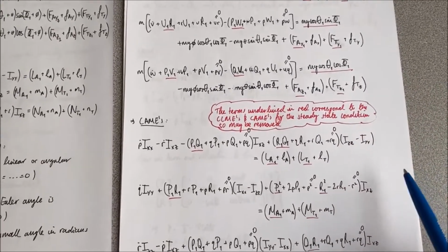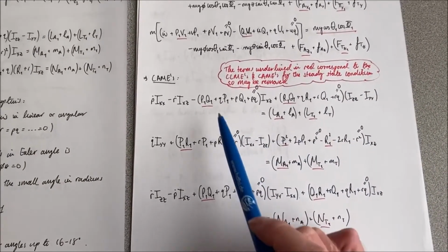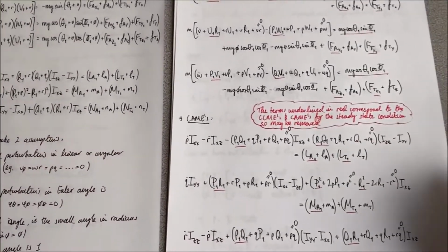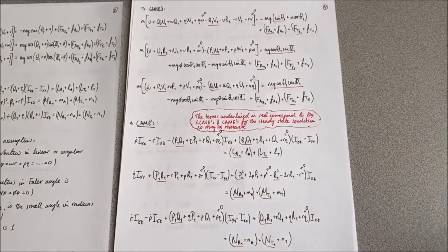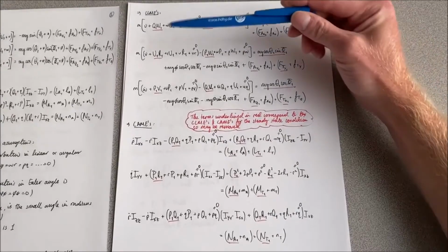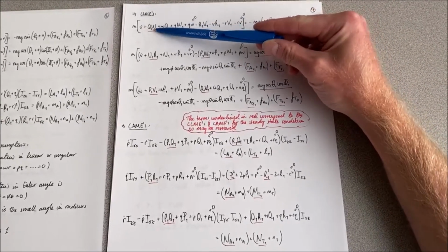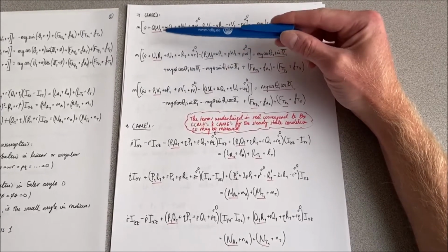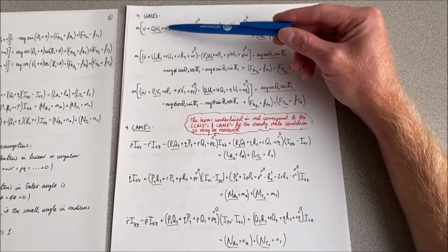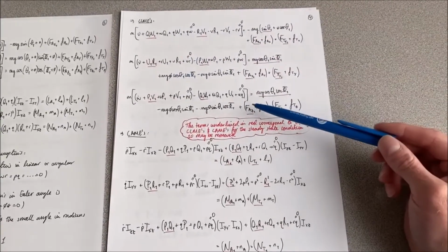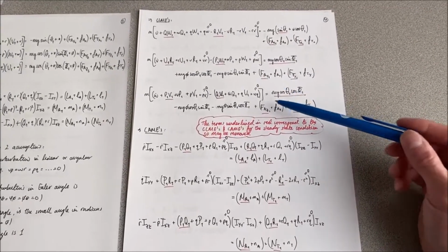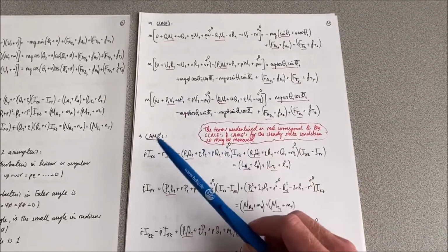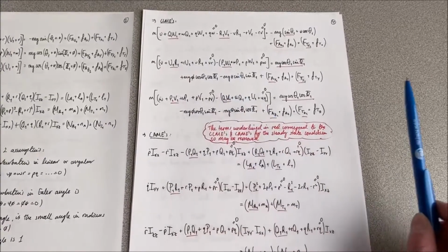And I've done exactly the same thing for the conservation of angular momentum equations, namely multiplied out all of those terms on the left hand side, like in here. Now, the thing to realise about what I've written down here is that all of the terms that don't include a small perturbation, so all of these ones, those are essentially the equations which relate to the steady state condition. So we can take those out, right, because we're only interested in what happens with this small perturbation. So any terms which correspond directly to the steady state condition we can take out as well, and these are the ones that I've underlined in red.